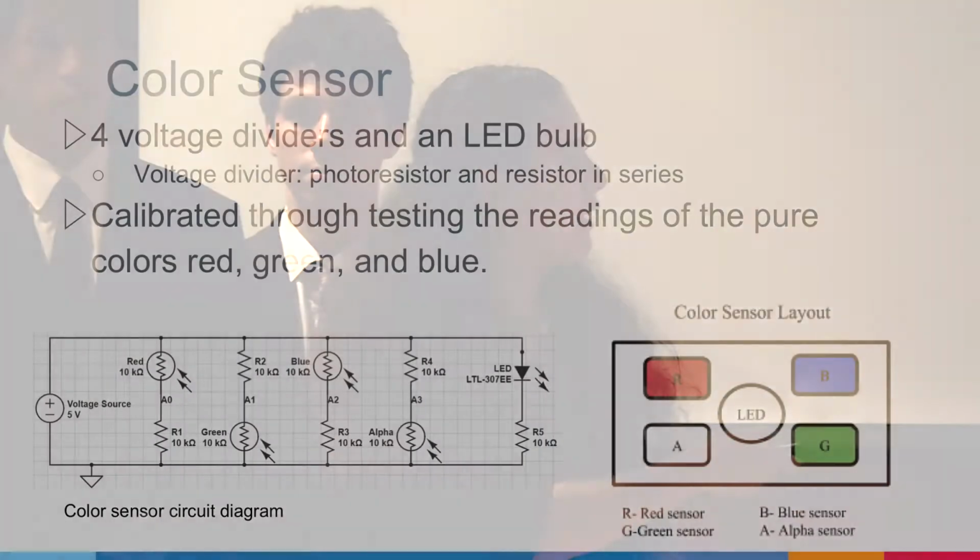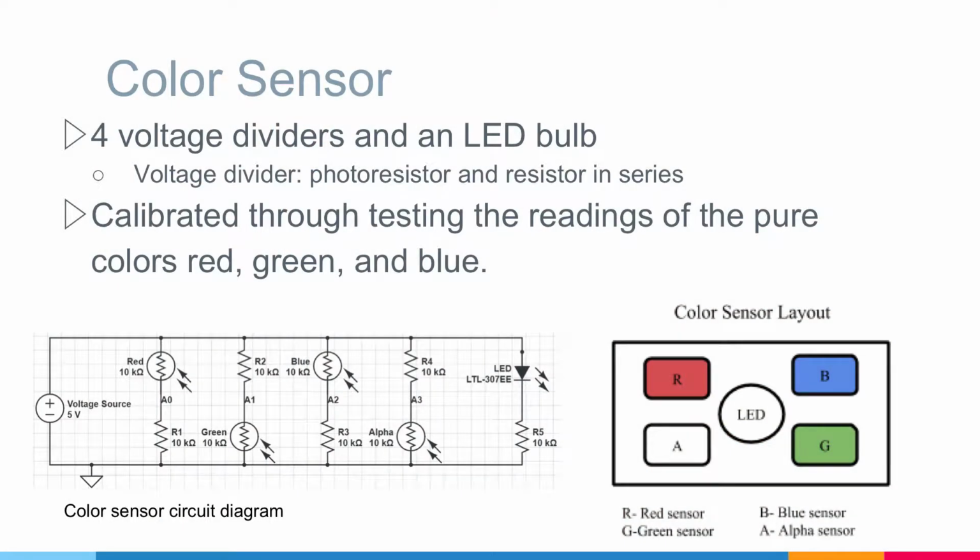So when you make a photoresistor for each individual color, as seen here, you can take the values that you read from the voltage divider, which could be any number from like 1,000 to 700, and you find what the max is and what the min is, and you convert that value to a value from 0 to 255 accordingly. And that's read through these pins. Using that, you can import it to Java, which is what we did, and display that color on screen using these values.